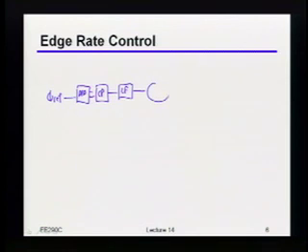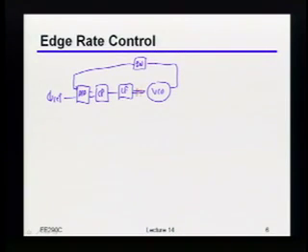It's the PLL control voltage, right? Okay, because remember, if we're doing, let's say, our typical dual loop CDR, we're going to have some PLL. That PLL is going to be essentially generating a clock frequency for us. All right, so I'm just going to draw the whole loop here now. Okay, so we've got a VCO, of course, that's feeding back into the divider, and then feeds back. Okay? Well, but notice this control voltage here, its exact purpose is indeed to tell the VCO what frequency you're supposed to be at, right?